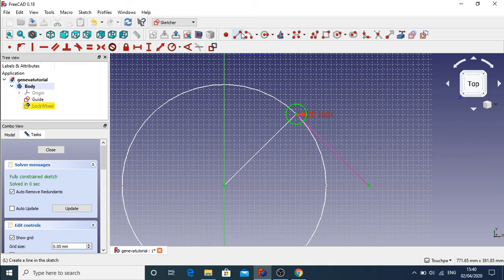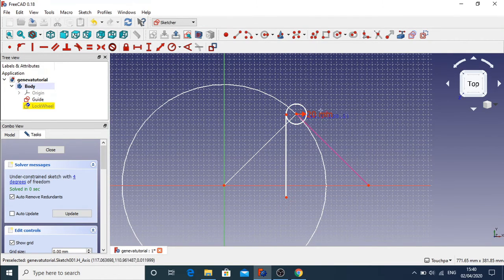So click on the line tool. Just going to bring the line down like so, and I'm going to press escape to get my pointer back and use the create a vertical constraint on that line, and also pressing escape I'm going to click on the top node and the circle and use the fixer point onto an object constraint. So that's all constrained up now.